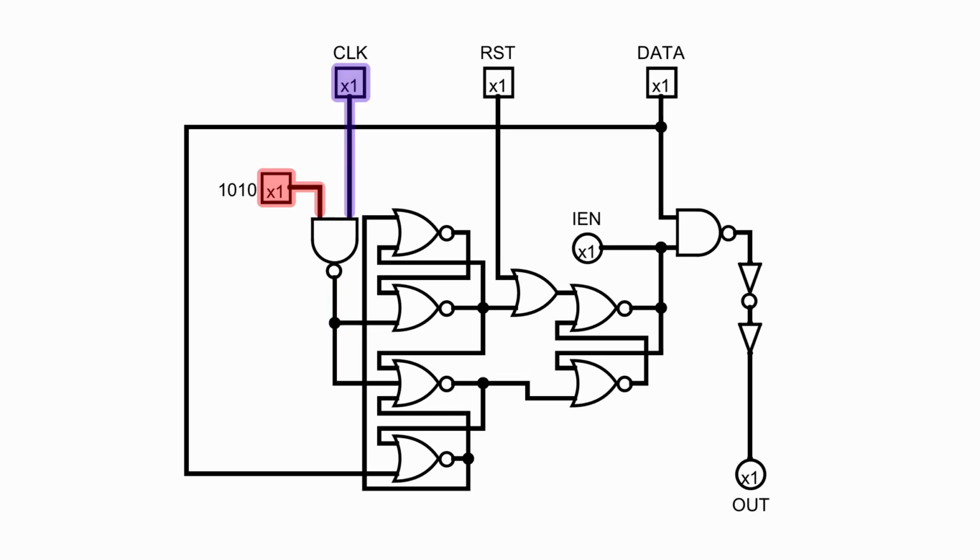And then if that instruction is set, whenever our clock signal goes high, the output coming out of our NAND gate will then go low. And that will initiate our D flip-flop to store whatever data is being input into the data pin here, which in this case is coming directly off of the 1-bit data bus.